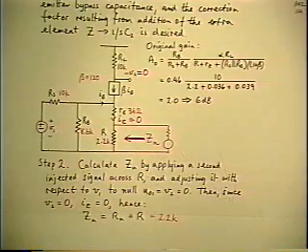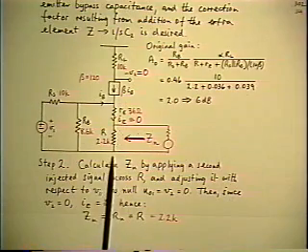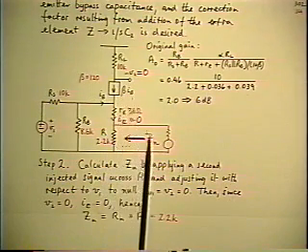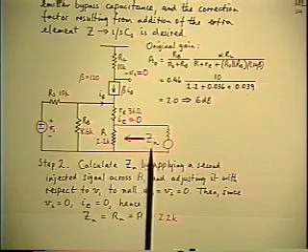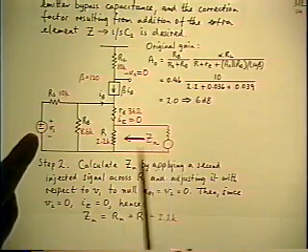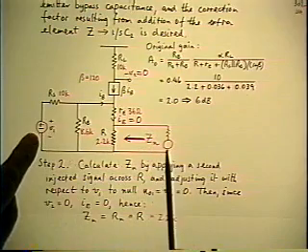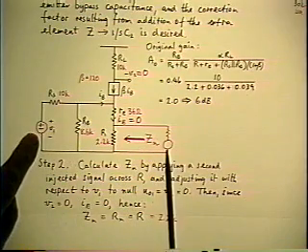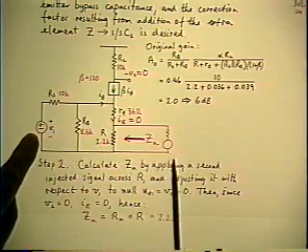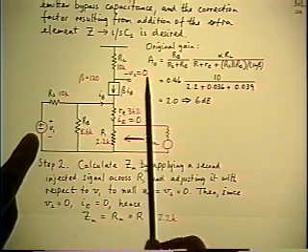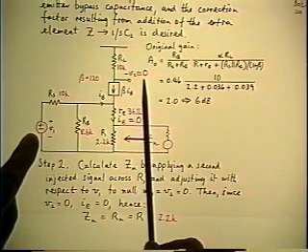In fact, let me repeat the derivation of the Zn yet a third time. Back to the first method again. Remember, the way you calculate Zn is you have both sources present, both the original input and the second source, for test purposes. You adjust the two of them in magnitude and phase until the first output nulls.